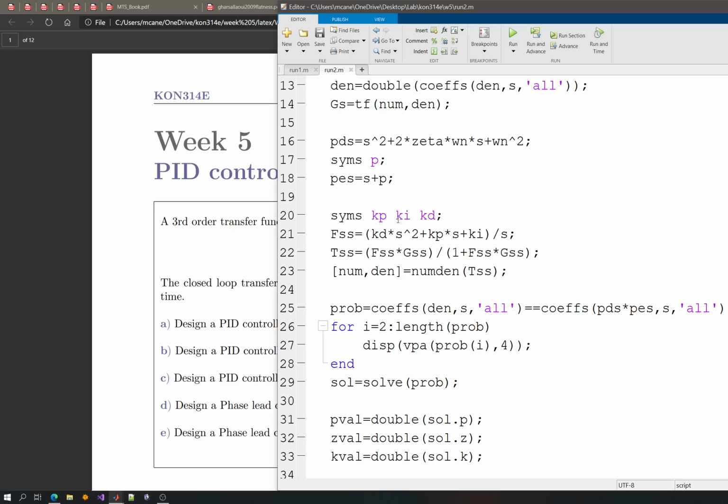So this is basically a pair of 2 unknowns. If I'm adding a pole, I'm adding a pair of 2 unknowns. Why isn't that the case for, let's say, 1 degree increment? If I'm just adding 1 pole, that pole is restricted to the real values. For a system of third order, if it's a real world application, it shouldn't have imaginary values in the transfer function.